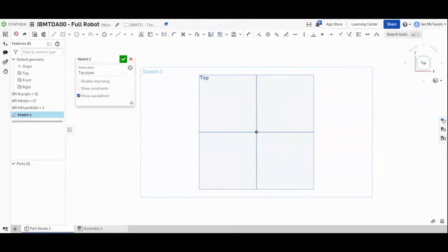So I'm going to undo. Doing it a second time just to explain. Rectangle tool, letter R. Construction tool, letter Q. Hold the mouse over the origin. When it's orange like that, you click once. You move your mouse up and to the right. Don't worry about the distances. And then you click a second time.